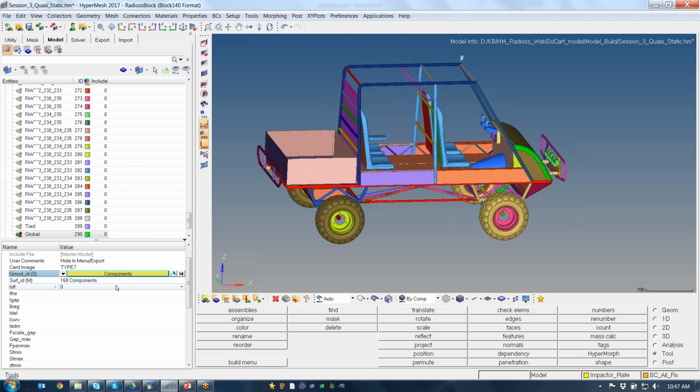Okay, fine. So I have selected the master and slave. Now I'm using some of our recommended parameters for the contact, which is IST4. I'm going with a specific gap option with F scale as 0.8. Again, these are the parameters which we go into quite in detail in our trainings: what is the relevance of these parameters and how they are working.